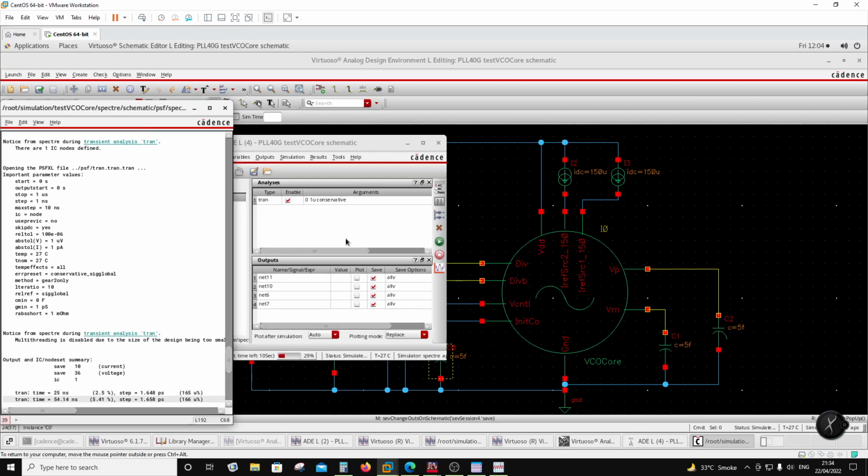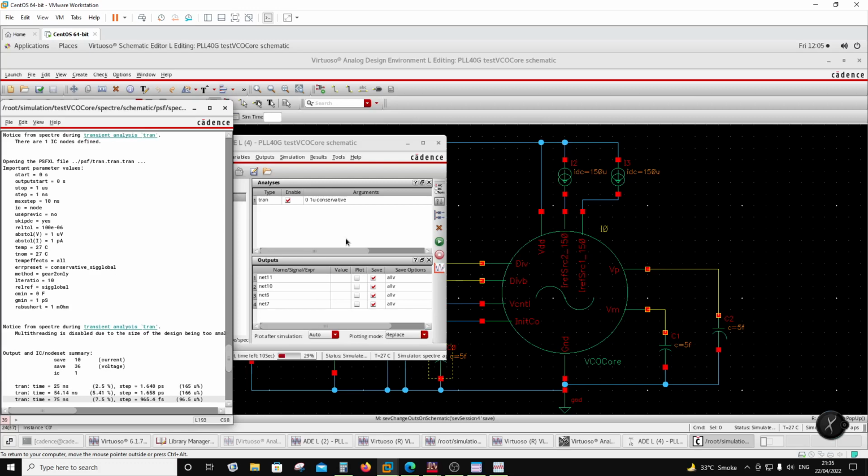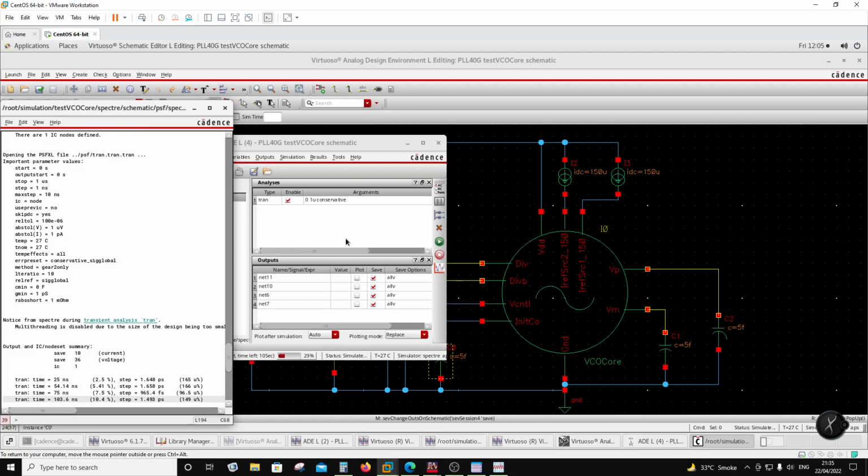So it's not always that you find DFT. What you can do is, there is an algorithm which takes the time period and inverses it, and that gives you the frequency, the instantaneous frequency. So we are going to use that algorithm to see what the frequency is. Seems like it's very slow and 1 microsecond is too large.